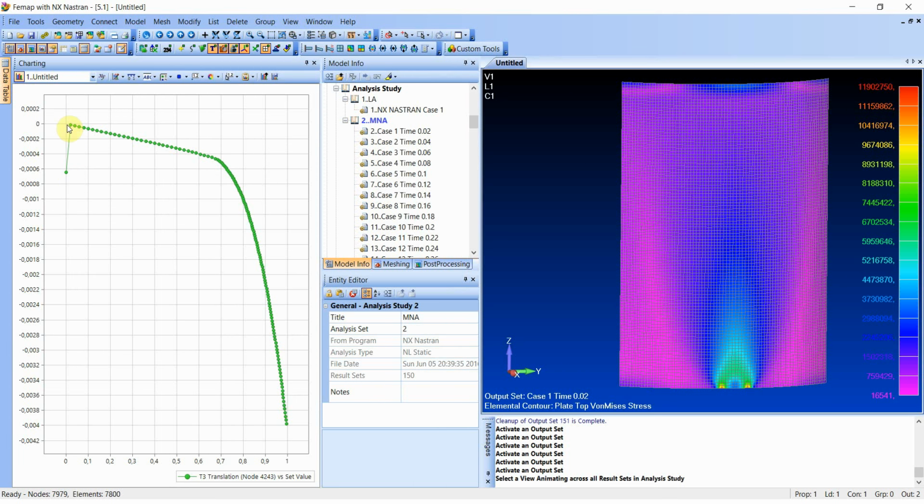Well, you can see that this is a stability plot, but rotated 90 degrees, and this is a displacement, and this is the load multiplier, which means this is 50 kilonewtons per meter multiplied with 0.5 here, for instance, or 0.8 here. So first thing you can see is actually that it always rises, that it does not collapse. In collapse we would assume that it should go up and then downwards, because the load is decreasing because the model is collapsing, as it is in geometrical nonlinearity.